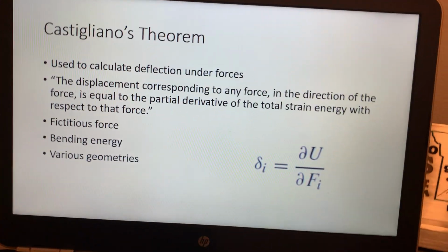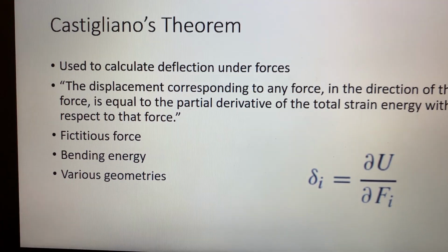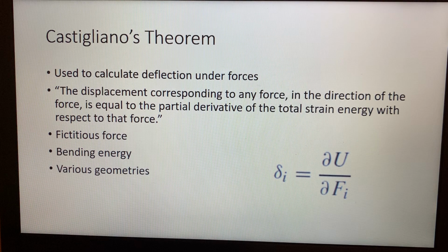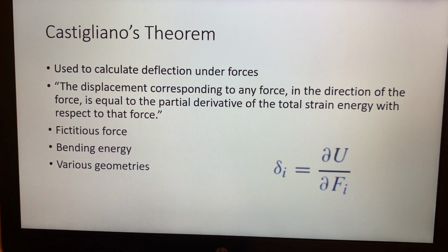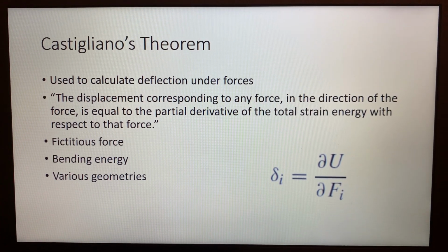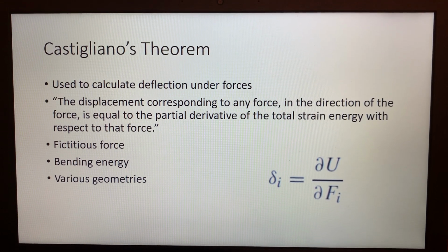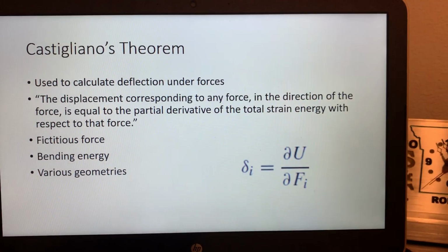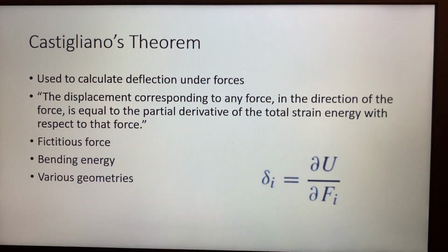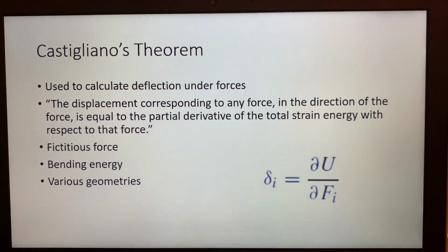One thing that we utilize with Castigliano's theorem is fictitious forces. That's something we place in the direction of the deflection and use to solve for the deflection. We have to know the bending energy, and we use Castigliano's theorem to solve with various geometries. So long as we keep with Castigliano's theorem's rules, we can solve these different complicated geometries.